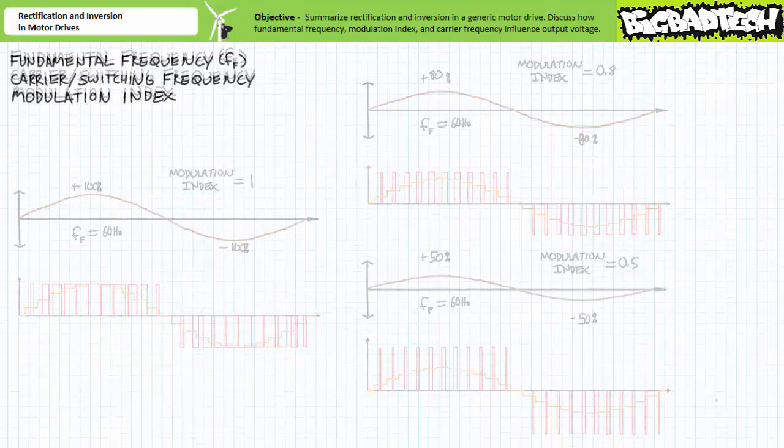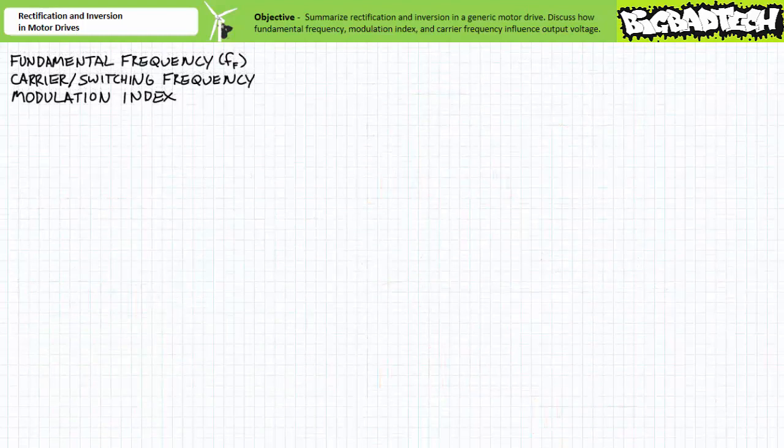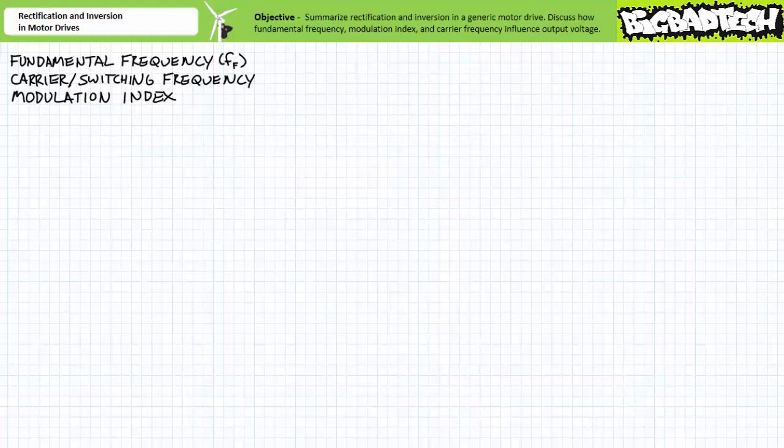I know I've shortcut some important details about filtration and the somewhat complicated math and technical details surrounding pulse width modulation, but 3 important comments must be emphasized about fundamental frequency, modulation index, and switching frequency before we put this to bed. First, the observant among you will note that fundamental frequency varies only the frequency of the resultant waveform and not the magnitude nor quality.